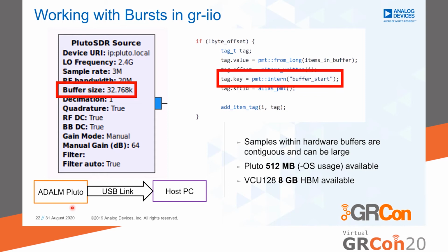Now, back in GNU Radio, what we do is emit a tag so that when we get a fresh buffer, we tell everyone downstream, hey, this is the start of a new buffer. Data before it might be discontiguous. Depending on how you build your flow graph, it may be possible for you to handle that. If you're talking about GR buffers, several GR buffers might be contiguous, but then you might have a break, and you could easily identify that with these tags.